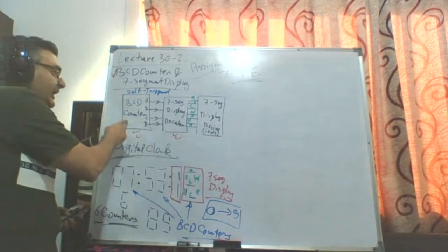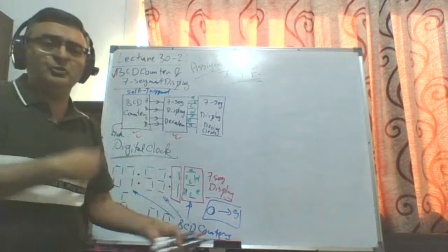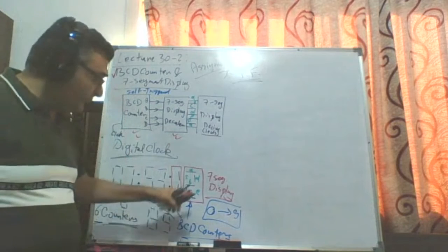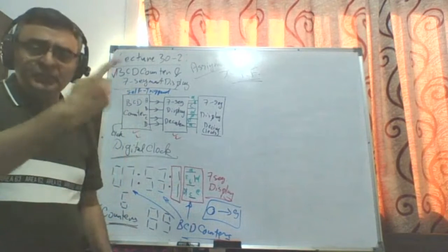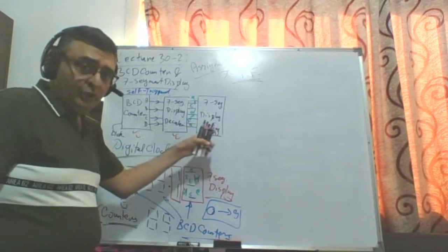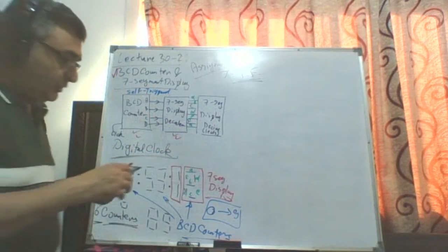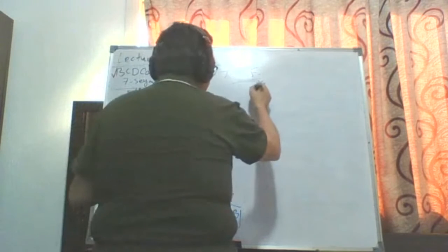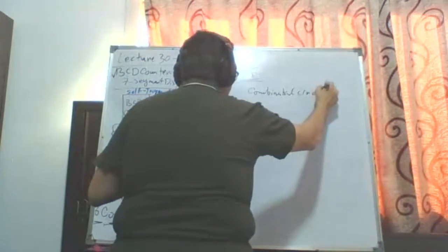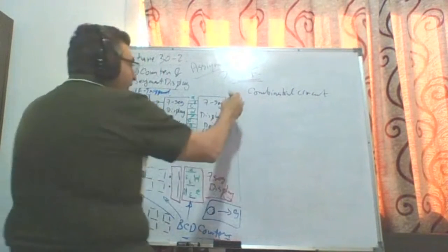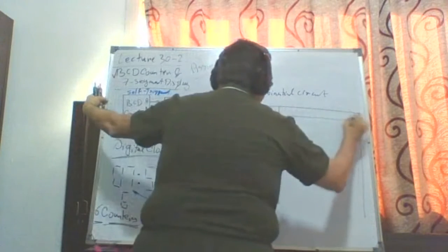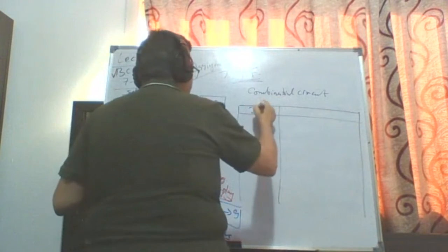A sequential circuit is the counter that actually gives me 0, 0, 0, 0, 1, 0, 0, 0, 0, 1, 0, 0, 1, 1, 0, 0, and so on, automatically. Every second, it will give me a different number. Now, I want to translate the number here on the bits here into an output to the 7-segment display. So, this is a combinational circuit from chapter 4. So how can I design this combinational circuit? This combinational circuit consists of inputs and outputs.